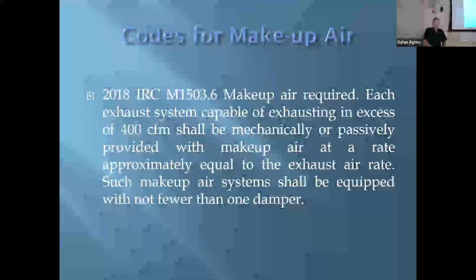The biggest exhaust system that I've looked at, as an inspection, was 1,600 CFM. And that was in about an 1,800 square foot house, and the furnace only put out 1,200 CFM. So we're talking about an exhaust fan that, if you're going off of the rating, could actually pump out more air than the system could even condition.